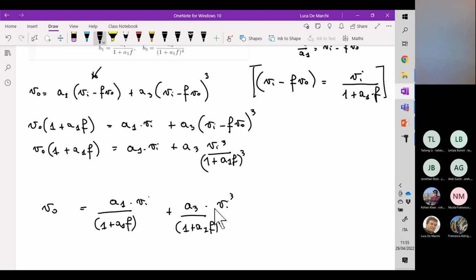So this is the idea. The phase at the 0 dB angular frequency must be equal to minus 135 degrees.